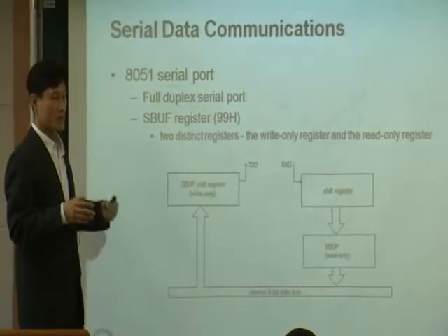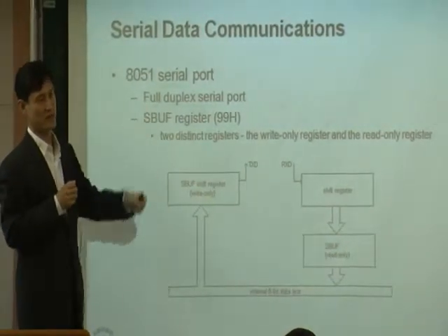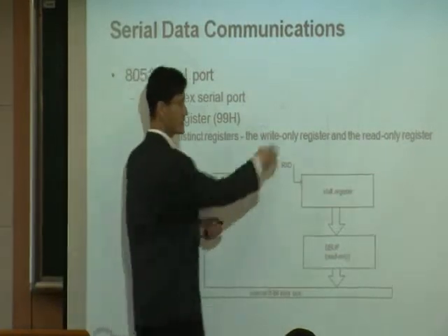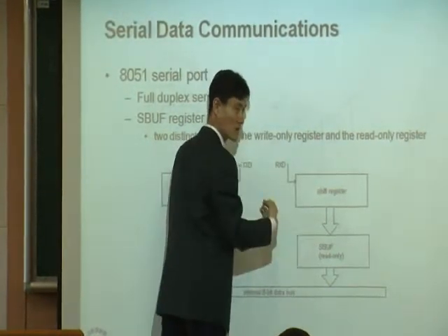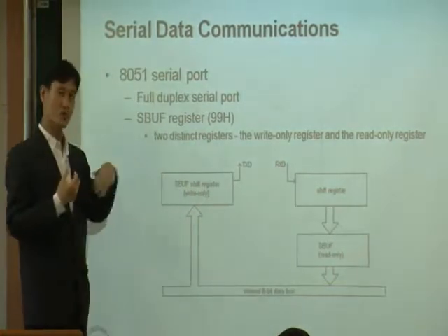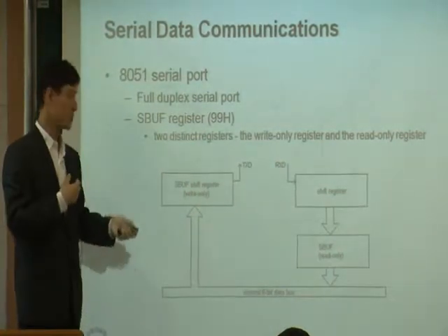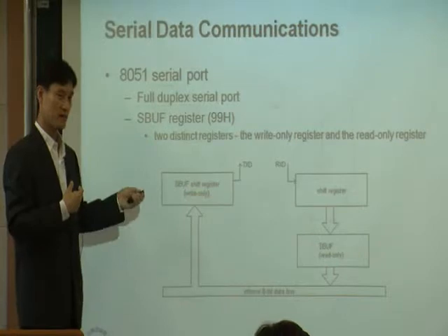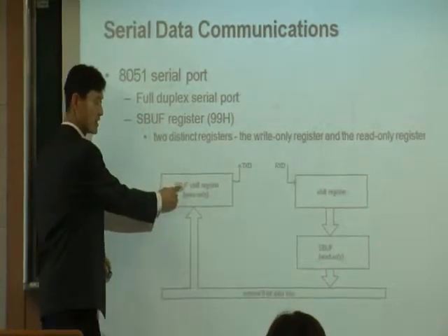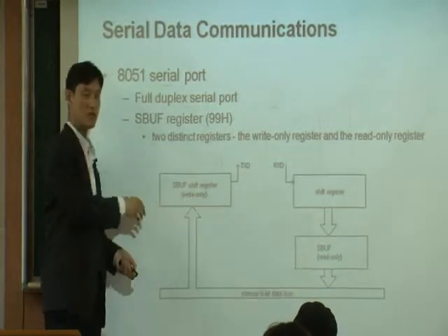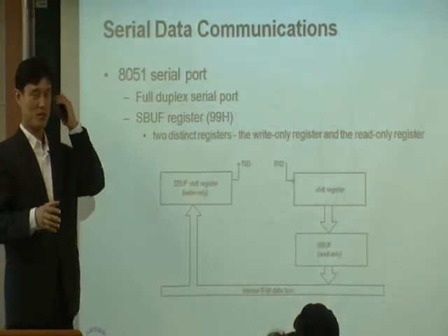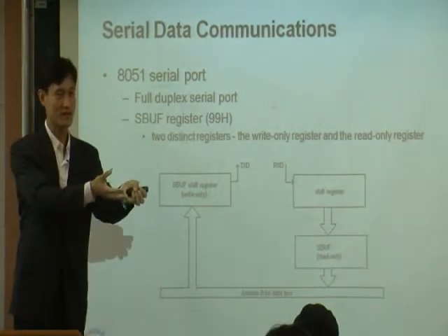Similarly, sometimes I want to transmit. This is the case of receiving. Okay, someone else is transmitting, I'm going to receive it. But sometimes I want to transmit. When you transmit, you are using this path. And this one is again the same name, SBUF, but this guy is only for write. Because when you transmit, you're going to write.